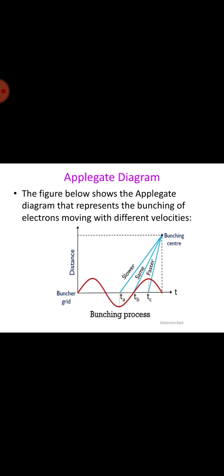The variation in electron velocity in the drift space is known as velocity modulation, as I said earlier, and the density of electrons in the second cavity gap varies cyclically with time. Such velocity modulation is not sufficient in itself for amplification by the klystron. While bunching, electrons exchange energy with the slower electrons, giving them some excess energy, and the two bunch together and move with the average velocity of the beam. As the beam progresses further down the drift space, the bunching becomes more complete as more and more faster electrons catch up with the bunches ahead.